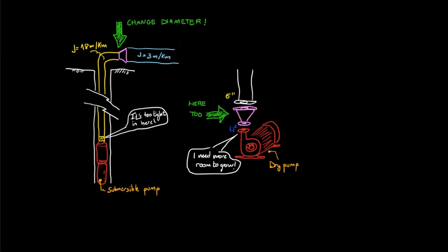One very common mistake is to match the pumping main diameter with the pump's outlet. Both borehole and dry pumps have size restrictions. The outlet diameters of pumps are usually too small. We need to increase it right after the valves that follow the pump.